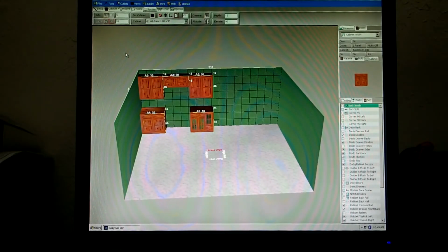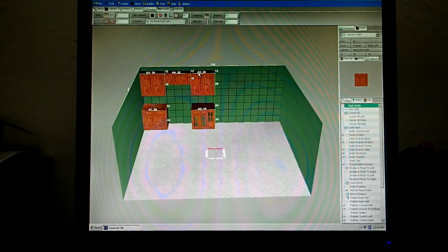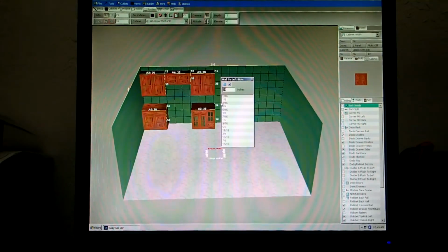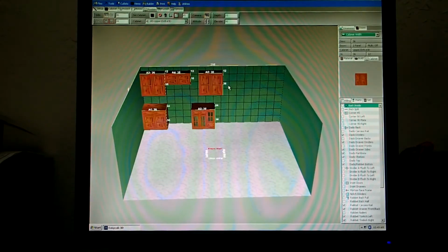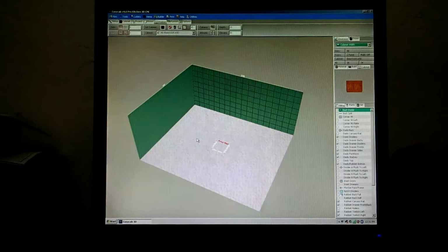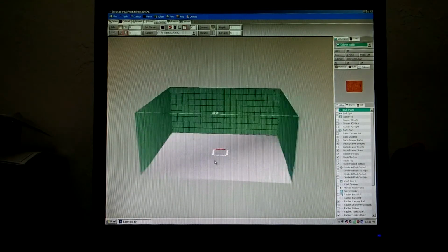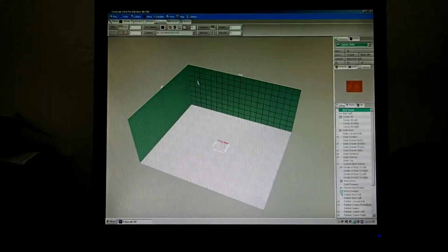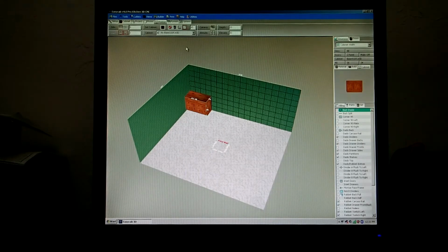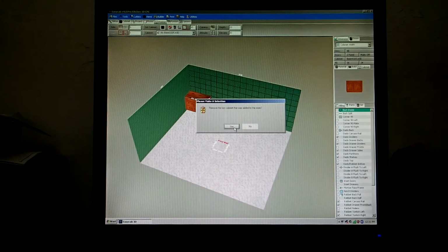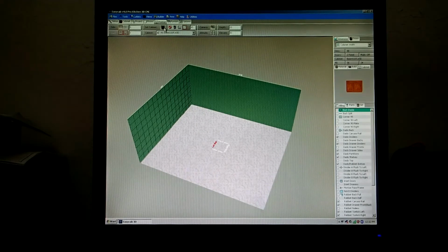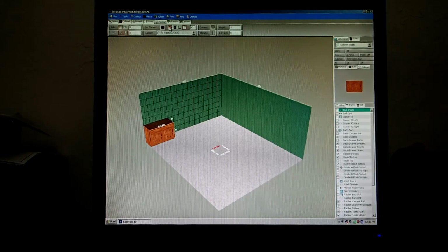Okay, if you need to move a cabinet, you can do that like this. Simply click on it, click move, and then if you type in like a foot down to the right, that moves it over a foot. The cabinets go to the wall that has the grid on it. So if you click the wall to change the grid, you have a room with 4 walls. Place this cabinet right here, and then we don't want it, we remove it. Click this wall, place the cabinet, remove it.